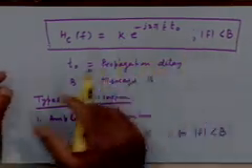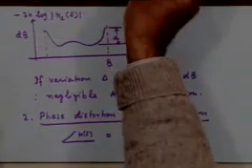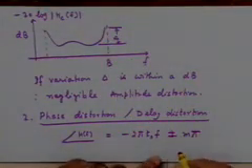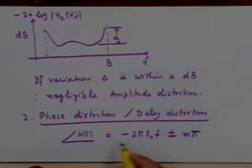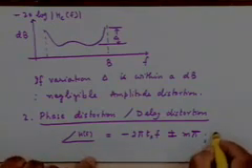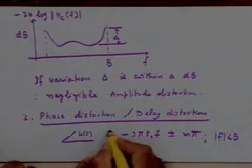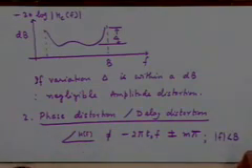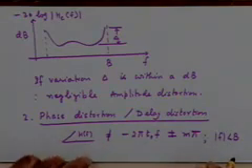So it does not really make any difference to the basic phase characteristics. So the required condition therefore really speaking is this plus minus m pi, right. So if this is so, there is no distortion over the bandwidth of interest for mod of f less than B. If this is not so, that causes phase distortion or delay distortion, right.